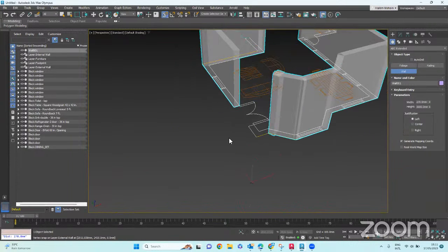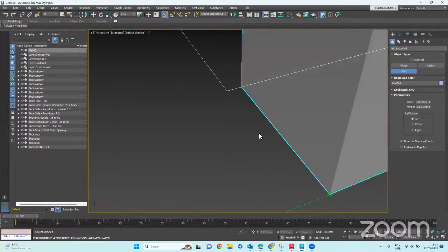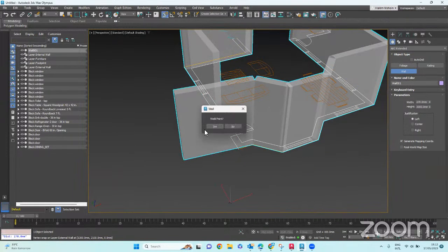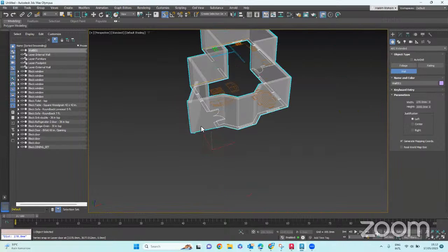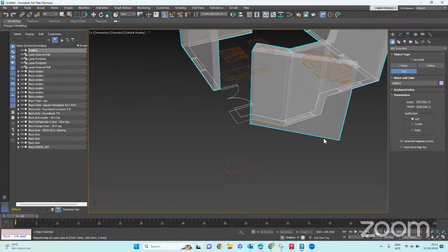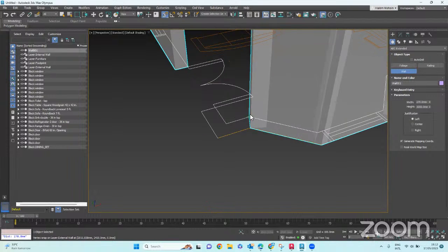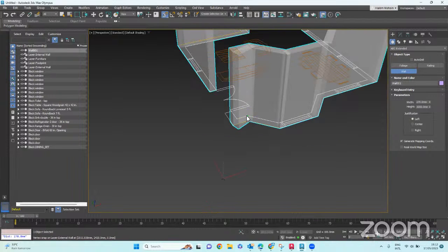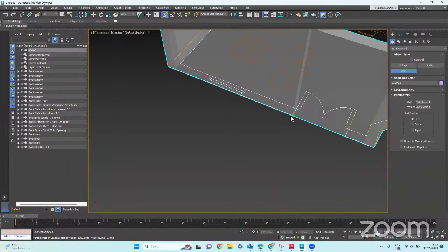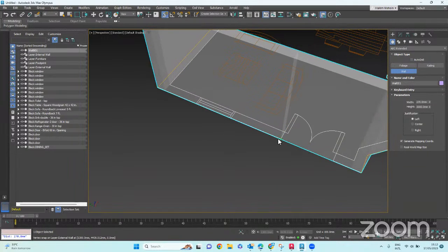If, for example, you've made a mistake and you didn't exactly click at where it should be, for example, you misclick here, and then you want to delete that part because this wall was continuous, you can just press backspace. Press backspace and continue with the correct position until you find the starting point.